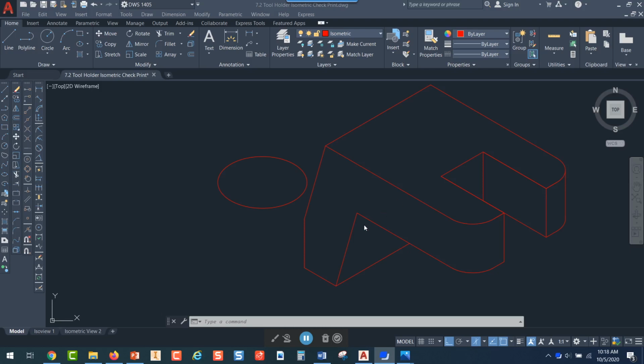In this video, I want to show you how to draw the tangency lines that go from this corner tangent to this ellipse over here. Then if we move across 2.5 from the end point of where that line would be, we would come in with another tangency line over here. Now, AutoCAD in later editions or releases has had a little trouble finding those tangencies, so I'm going to walk you through it.